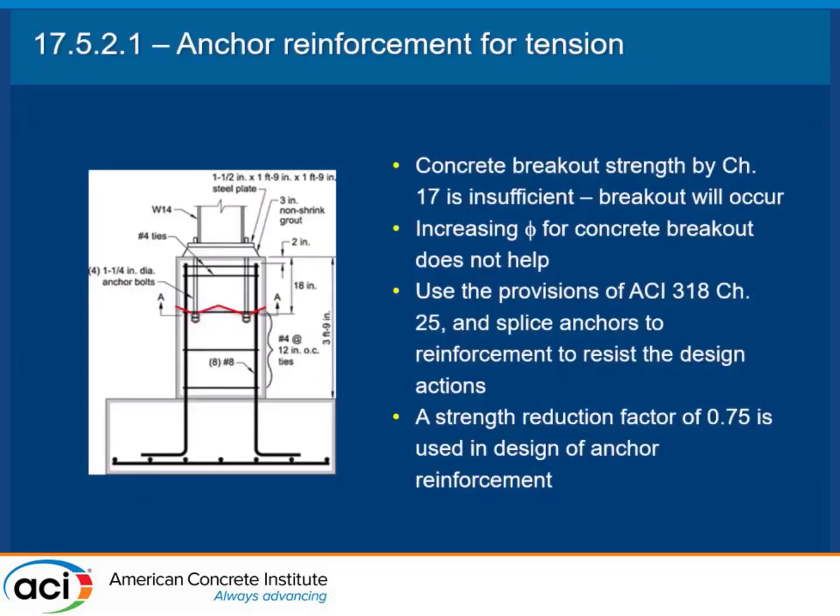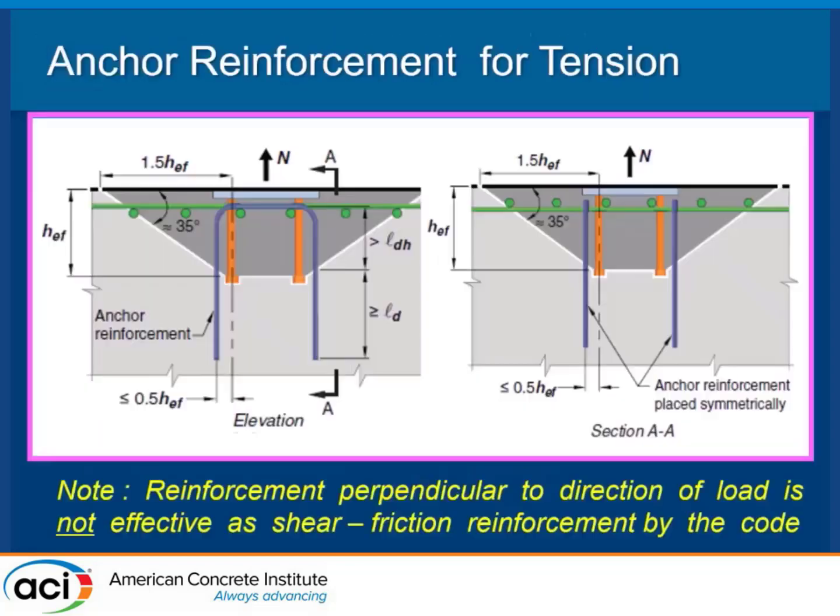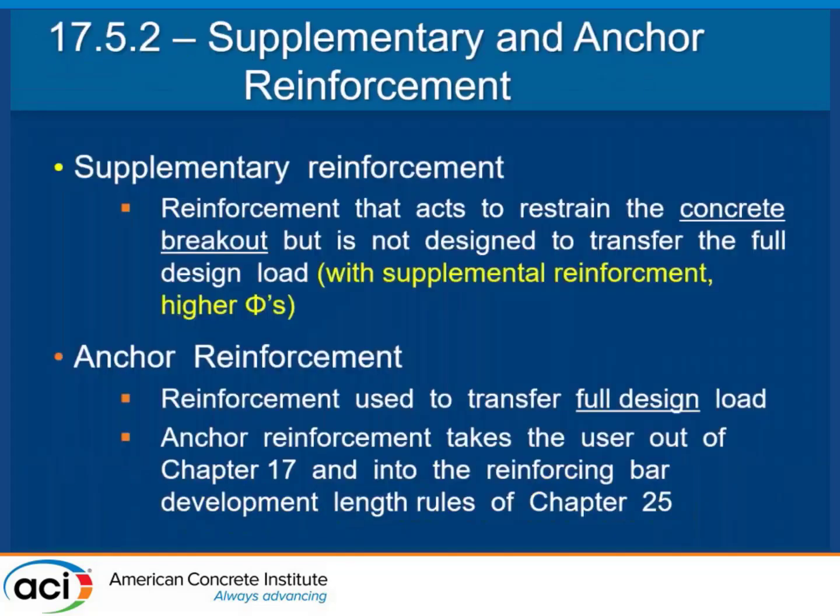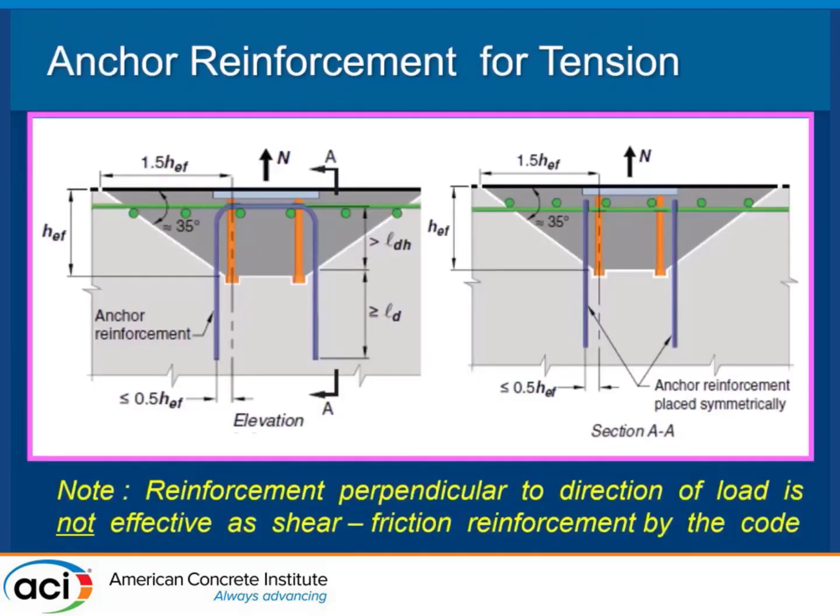Matt? Yeah, I think you have a question. Oh, yes, sir. I've not asked on the previous slide before, I forgot. Maybe I'll ask. So here, for example, if there's reinforcement here, I guess for axial load, and the bars that cross that anchorage plane, is basically into a beam, for example. Yes. Would that qualify, or does it need to be a bar specifically, like a square loop, that passes? No, you're just trying to anchor that breakout.